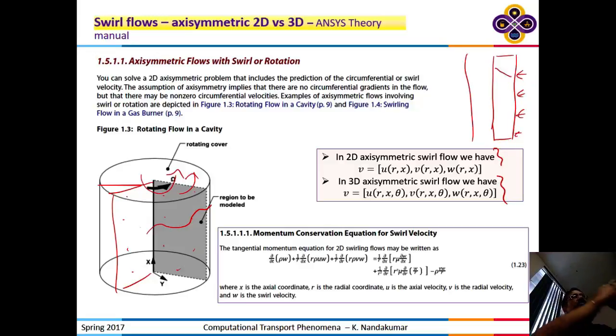But once that becomes unstable, you have flows that have these cells. So what was continuously translatable now becomes discretely translatable, meaning if you move this by one wavelength, you get the same pattern. That you call discrete symmetry. So the symmetry along the z direction is broken into a discrete one. But it is still continuous in the angular direction.